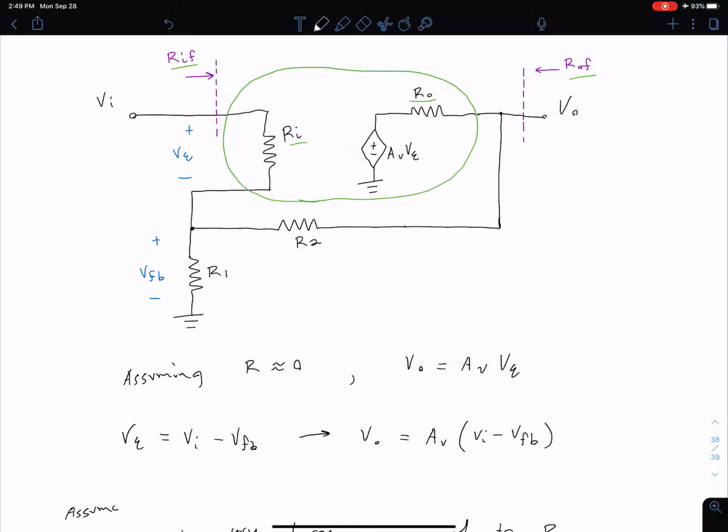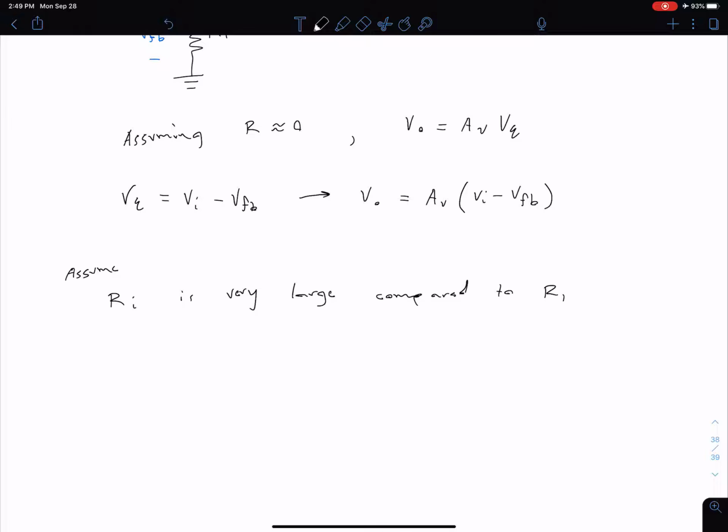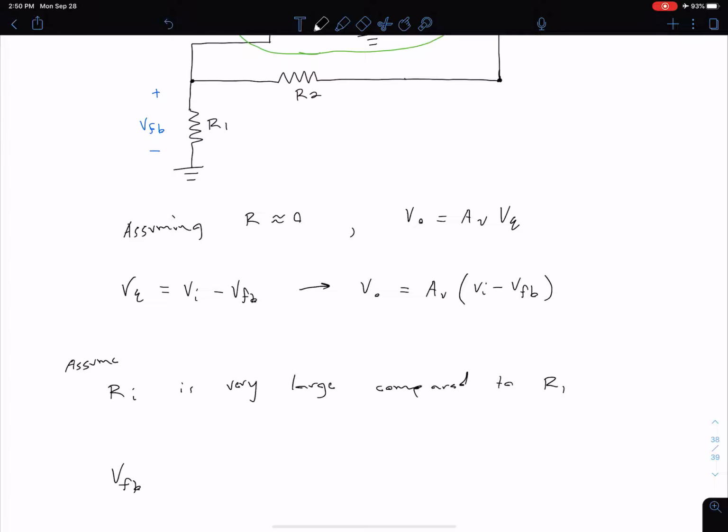If we ignore that Ri, we're covering this up, saying don't focus on that. We see we do just have the simple voltage divider of V naught dropped across the combination of R1 and R2. So let's write that explicitly down here. The voltage across our R1 value is equal to VFB. Scrolling up just a little bit, keeping in mind this is V naught, that's just a little off the screen. So VFB is going to equal V out times R1 divided by R1 plus R2.